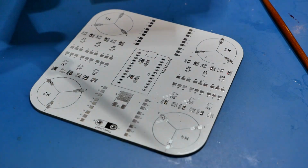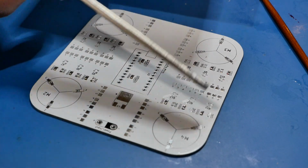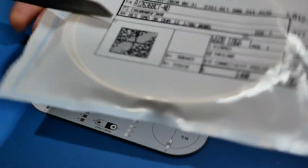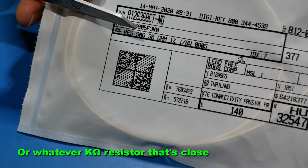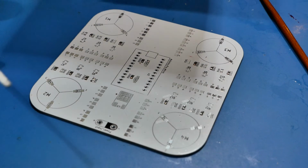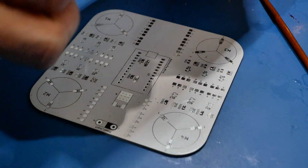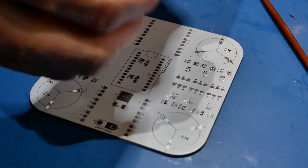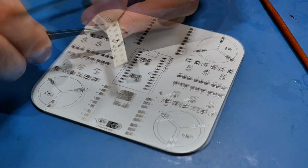Okay, so same thing as last time. We're just going to go ahead and solder all the 0805 resistors into the 5K spots, but we're going to go ahead for now and use the 3K ohm resistor. That should be sufficient to get us started. It should work just fine. And then maybe later down the road, we or you or whoever, we can decide on if we want to desolder those and try playing around and see what different values do what.